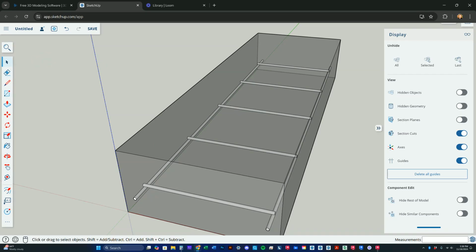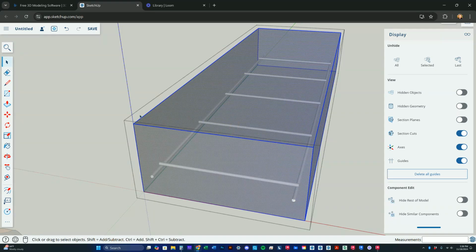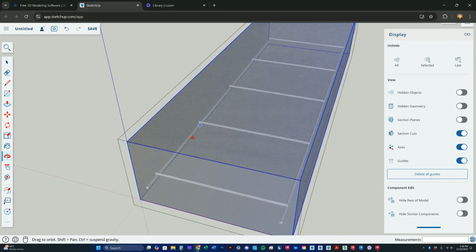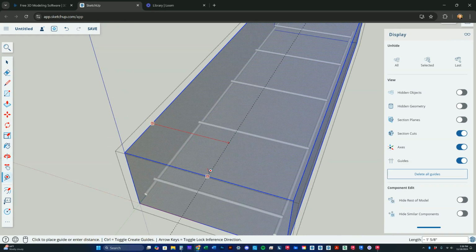So according to the assignment, we're going to build an 8-inch wide by 8-foot tall concrete wall on top of this. The footing has to be keyed so that the retaining wall doesn't want to slide off of its footing.